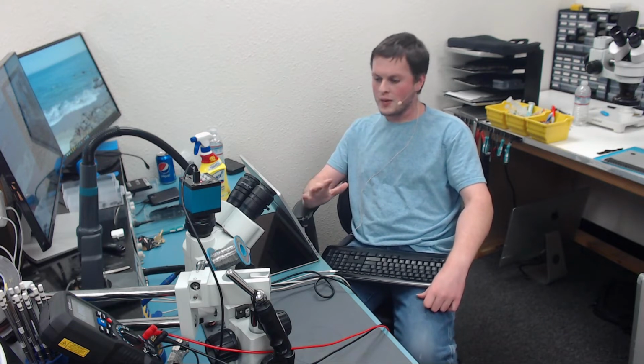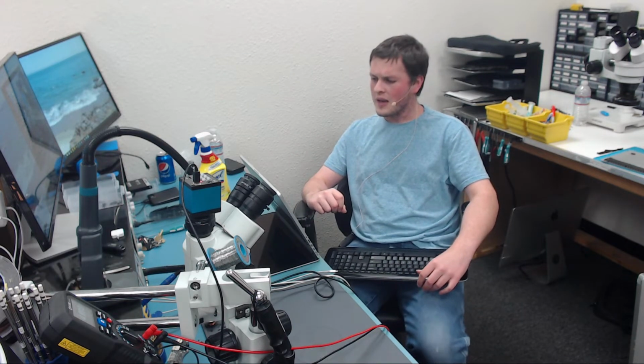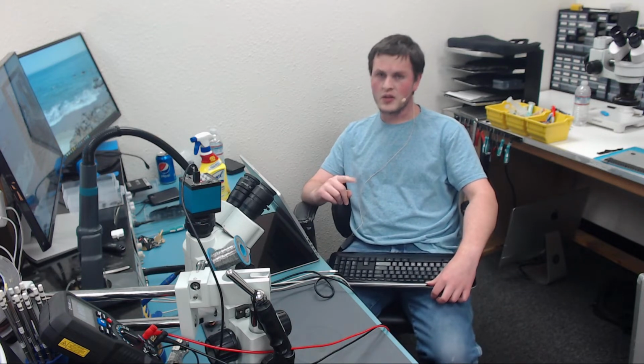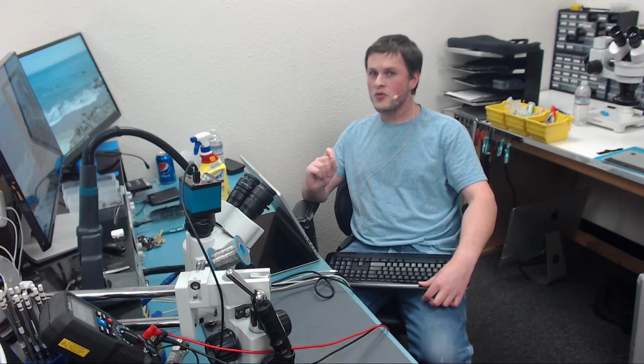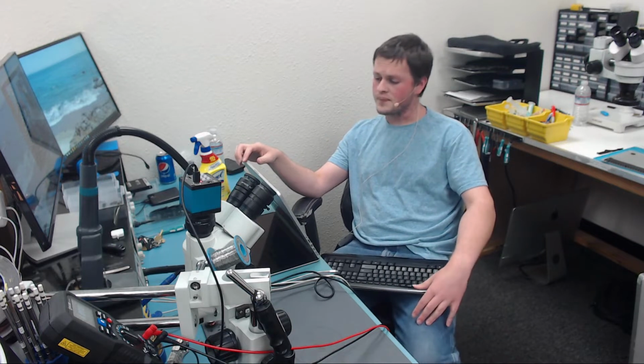Let's go over how this presents if you see it in your repair shop. Loss of video, that's the major one. Sometimes it'll be fine when it's cold, and once it gets hot, you'll start getting black screens. Sometimes if you set the computer down, the screen will go black. Other times it'll just randomly go black. Kernel panics are another common one, very common under load. Very, very rarely, video distortion. If vCore drops too low real quick, you can sometimes get a little bit of video distortion. It is very rare and we really don't see that, but it's not out of the question.